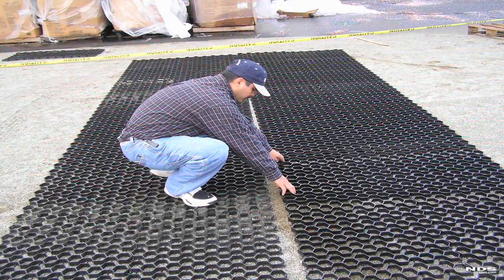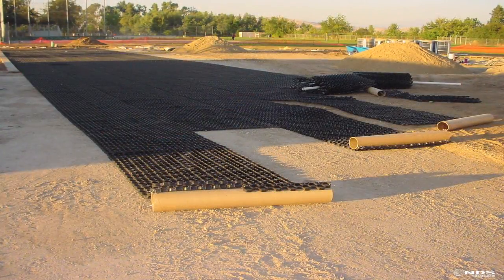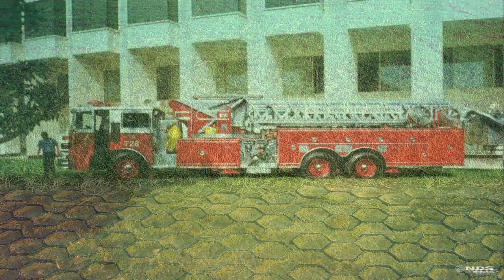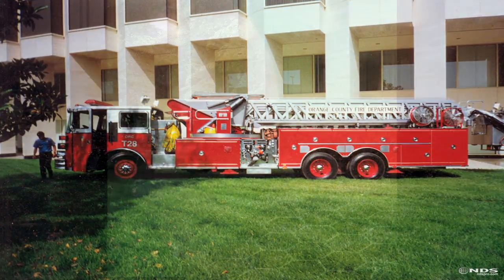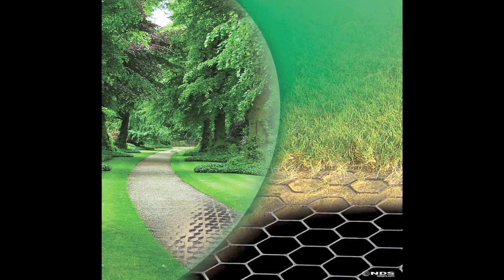Often with these systems, I end up putting a triaxial geogrid down in the system because geogrids are a really nice way to get some strength to the section without having to put a lot of rock under the system, and particularly if there's grass in there. It's really nice to use like a coarse sand or something that the grass can actually root in, but then have a geogrid down there to get the kind of structural capacity that you need.